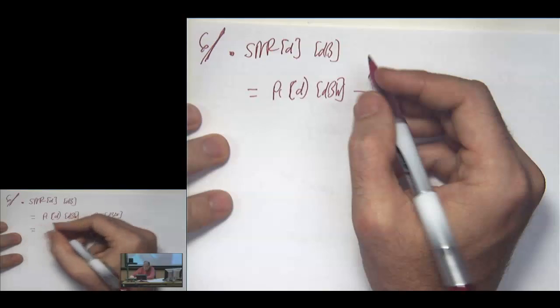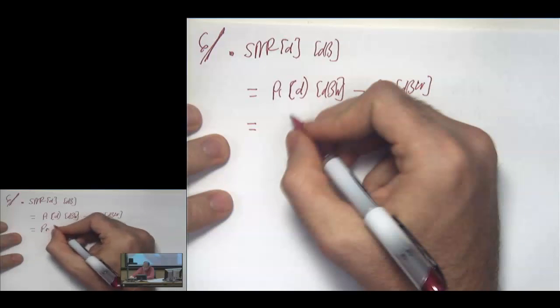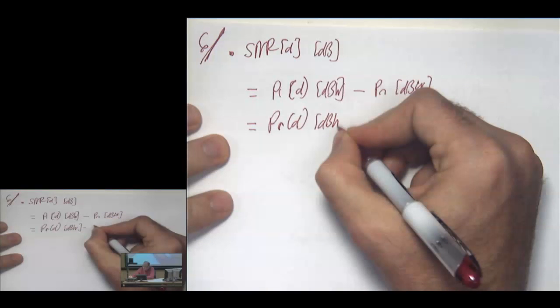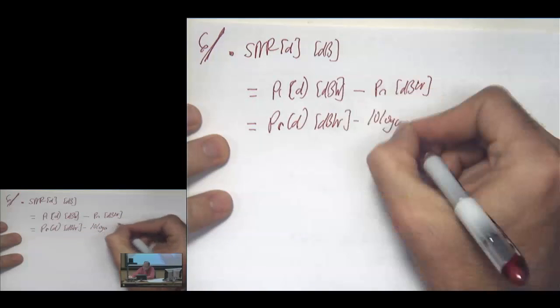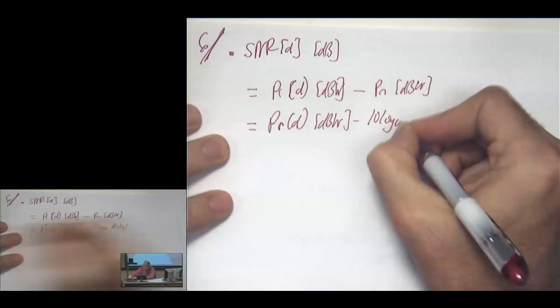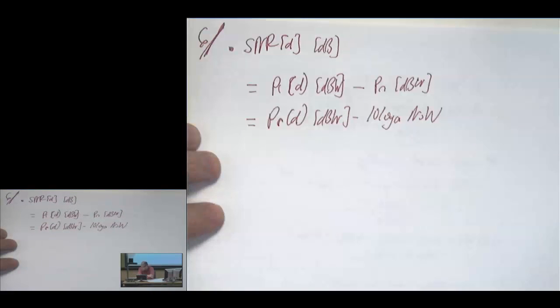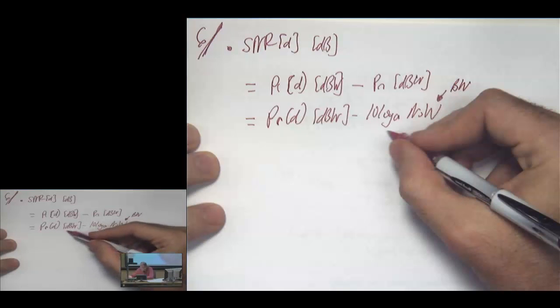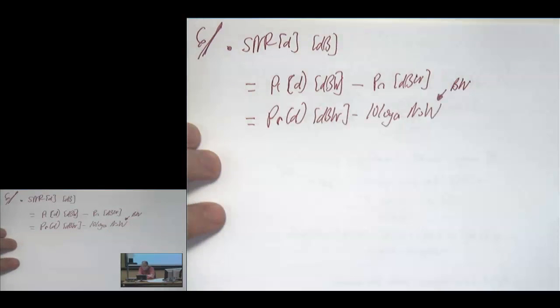And then, for the most part, you will use received power minus 10 log 10 of N naught times the bandwidth here. Sorry, there should be bandwidth there. So this would be the noise power, and this would be the received power here. So what you can see is that the SNR also varies as a function of distance. The only difference being the constant here.